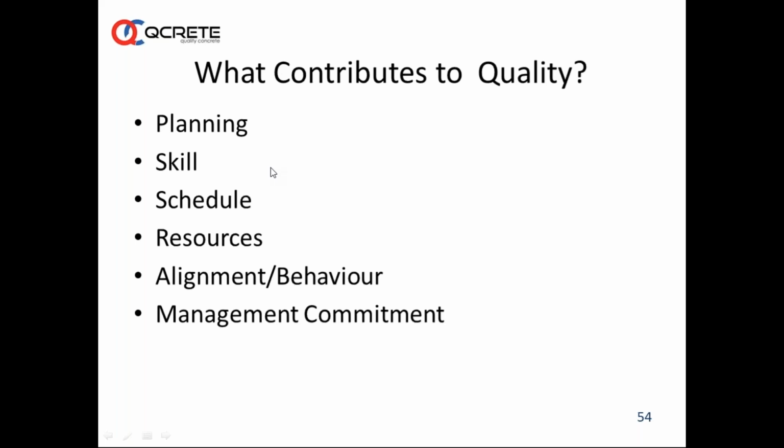Mr. Amarnath is again asking, what are the advantages of Readymix concrete? It is a factory produced product. All the ingredients meet the requirements of relevant IS standards, and all the ingredients are selected and tested continuously. Each batch, each consignment is tested to meet the requirements of relevant IS standards, and the final product also is assured. So it comes with a quality stamp, and you can quickly lay the concrete. The pumping rates are high. You can lay the concrete faster, do your structure faster.